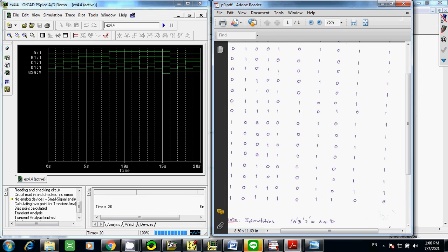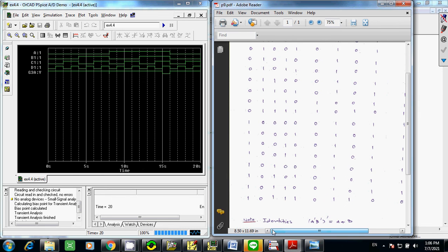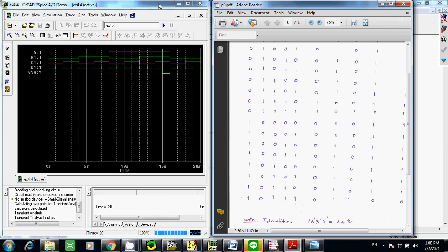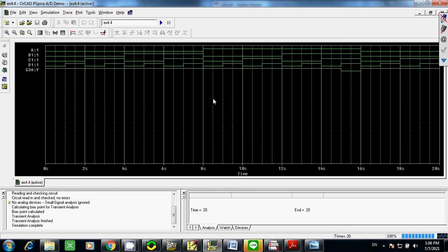And you go to check your input. So it's A, B, C, D. So it's from 1, 1, 1, 1, which gives you output 0. You go to check. So all inputs are 1, right? You can introduce your cursor here. This is very nice about PSPICE. If you click on the segment, this will show you the logic of your input and your output.